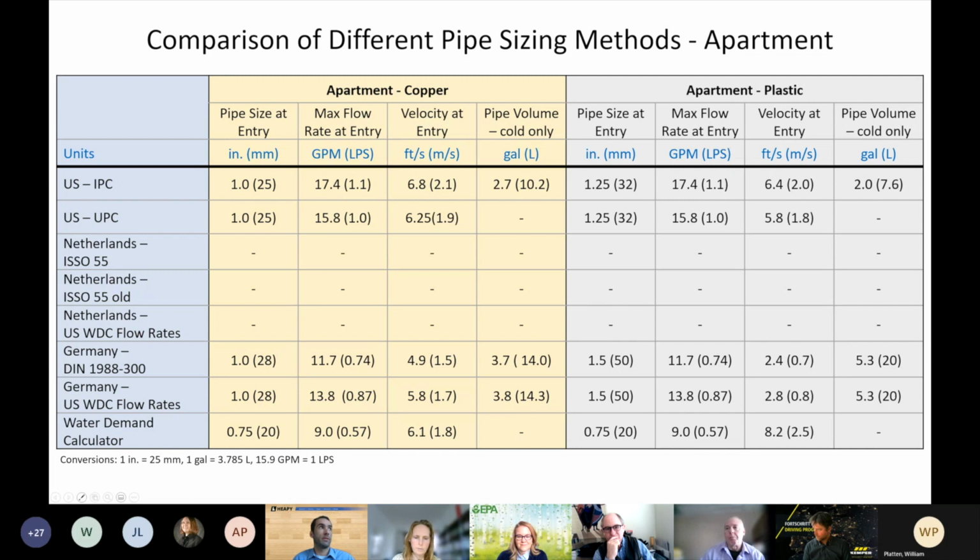Yeah, it's very much a cascading effect because you have slower flow rates, so you have biofilm. The biofilm is getting attacked by the chlorine, so the chlorine attacks something and it's done. It doesn't just attack something and move on to attack the next thing. So it's dropping the residual as it goes through the building. So the larger the pipe, the less likely you are to get enough chlorine at that tap. The most remote branch of your building isn't going to get the same amount of chlorine as the very first fixture off the main coming into the building. So yeah, the larger the pipe, the less likely you are to get good chlorine within your building.